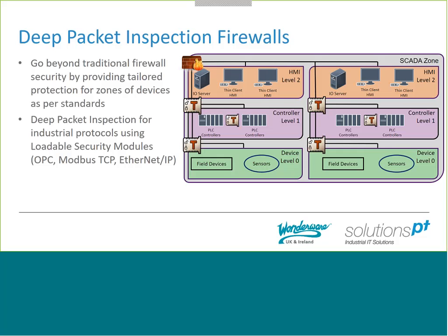So, like I say, they're designed for the industrial space. What's kind of cool about them is they're undiscoverable on the network. So whilst you're configuring them, they will pinch an IP address or something downstream from it, so that you can configure it. And when you put it into live mode, it just disappears. It's undiscoverable. And because it's designed for the OT space, it understands our protocols.